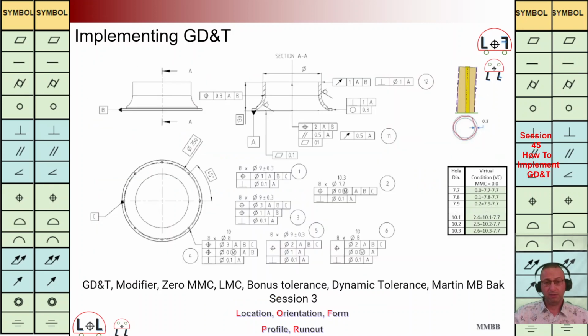The same as always, we are going to have these datum references. This area is in contact. Let us call it reference plane A. For now, let us consider this datum axis B here as a secondary datum reference. And then in order to fix the coordinate system, we are going to consider this datum axis C here, as we can see here.